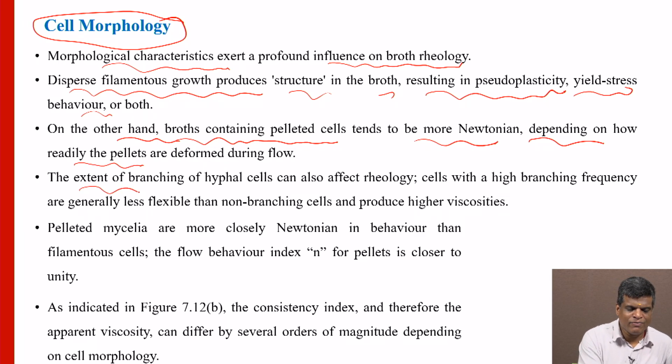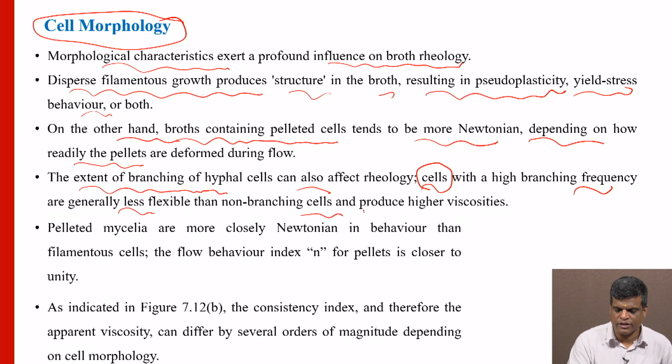The extent of branching of hyphal cells can also affect the rheology. Cells with a high branching frequency are generally less flexible than non-branching cells, and of course they produce a higher viscosity.